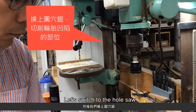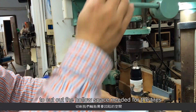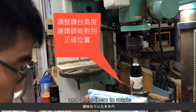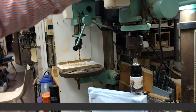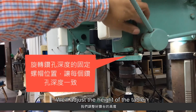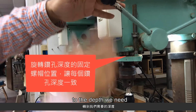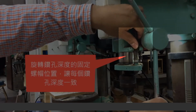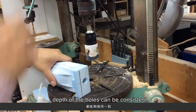Let's switch to the hole saw to cut out the hollow space needed for the tires and allow them to rotate freely within the car body. We'll adjust the height of the table and also adjust the milling nut to the depth we need, so that later on, the drilling depth of the holes can be consistent.